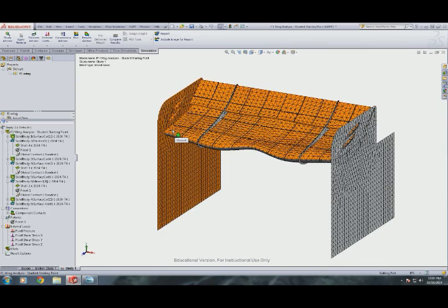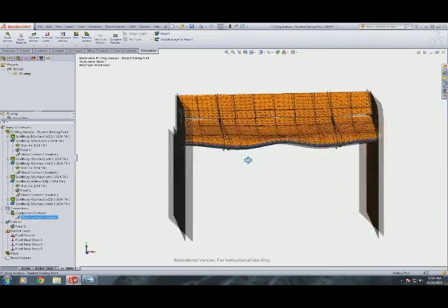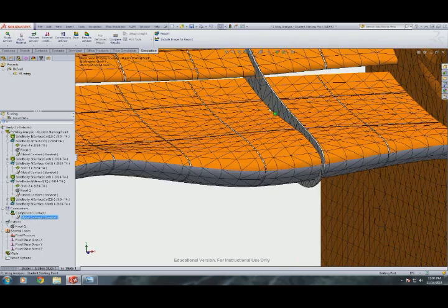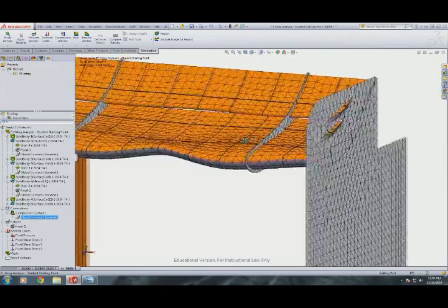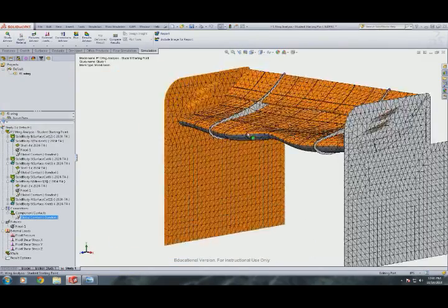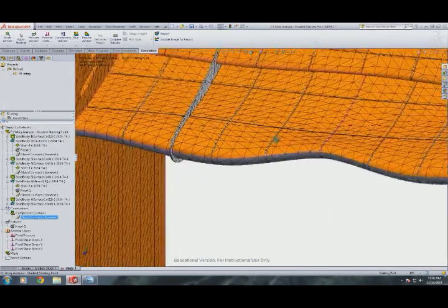So this wing skin is automatically connected to the ends by this global contact that's automatically put into finite element analysis simulations. Also, since this solid part has the inside cut out for the surface, those are already under global contact. So everything in here is already taken care of by that global contact constraint, except for the bonding of the internal structure to the outside skin.